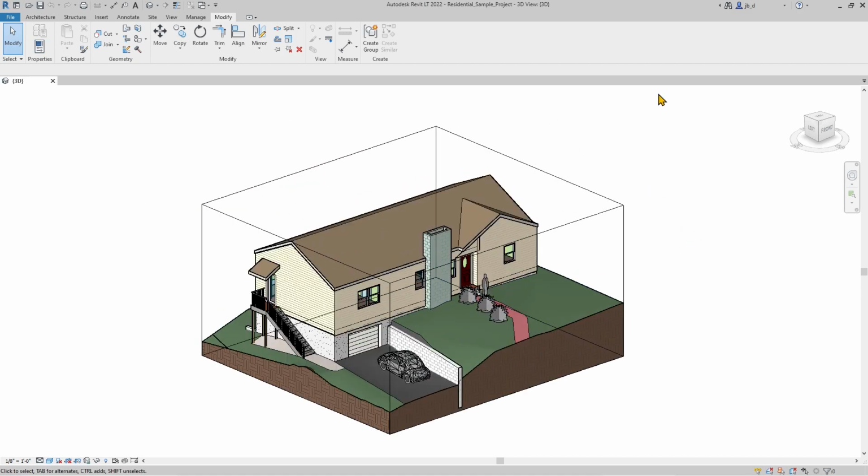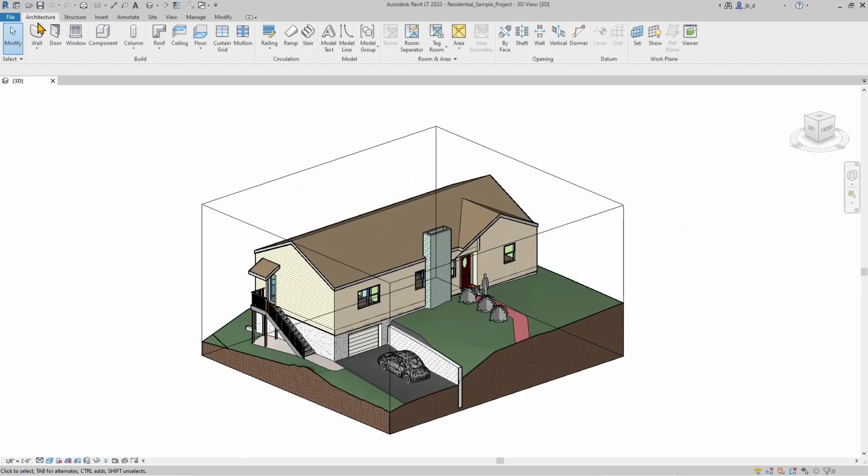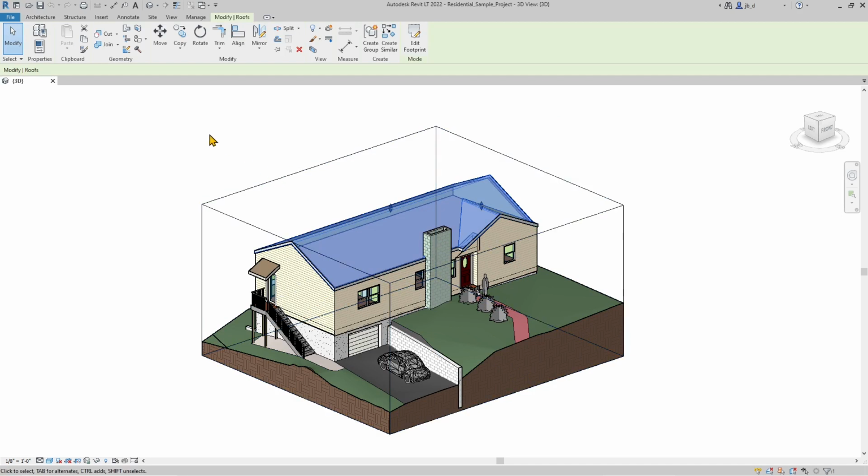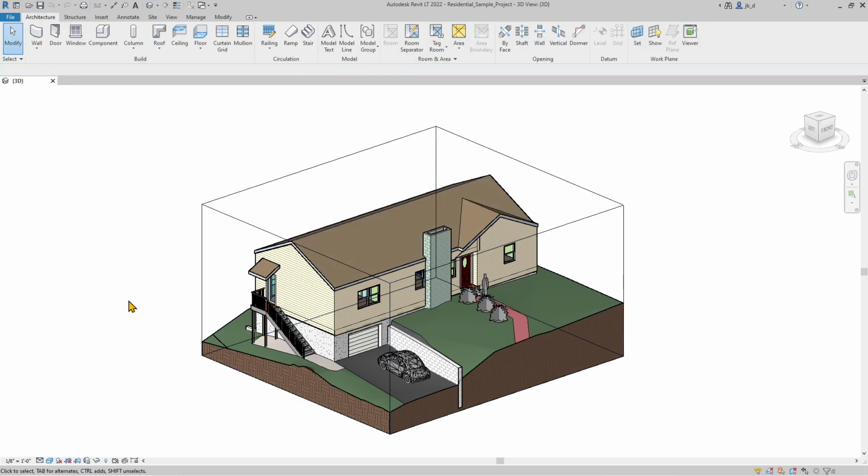And you will find Revit like this, and you say, okay, nice Revit. This is really nice, but I cannot do anything. What am I supposed to do here? I select this, and I can modify it, but where are my other views? Where's my project? Now, this is easily done if you're a beginner, but I will show you how you can fix that. Now, make sure that every time you open up Revit, you will find those panels that are paramount to work in Revit, which are the properties and project browser.